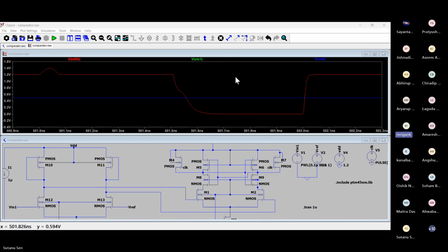But for AC analysis, you need the entire operation to be small signal. That is not true here. It is not working in small signal mode. It is transitioning from the initial small signal operation to complete large signal mode, right? It is latching. That is why it is not a continuous time circuit. It is a clock driven circuit, and it is working in large signal mode. There are many discrete time circuits where you have clock driven units. There are ways of doing frequency response of those circuits which are clock driven.